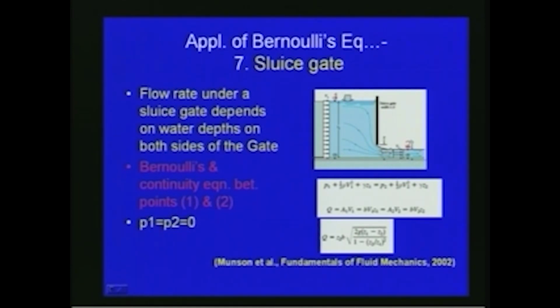So, the sluice gate is here and the liquid level is at this level and the flow is coming in this direction. After the gate, again as we have seen, a vena contracta will be formed, that means minimum cross sectional area where the streamlines will be parallel, and then we will be applying the Bernoulli's equation between section 1 and section 2, where the area of cross section is minimum. So, here applying the Bernoulli's equation and continuity equation.